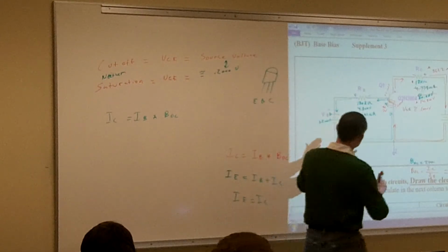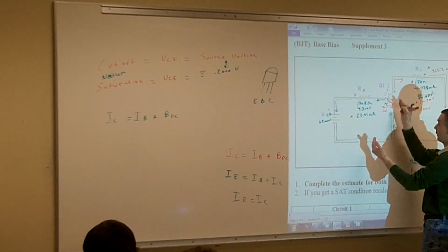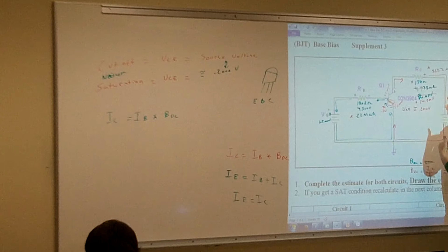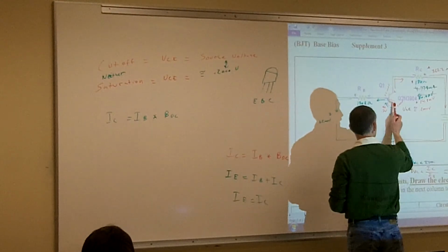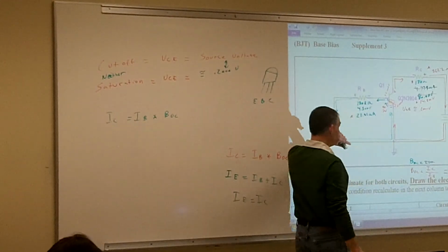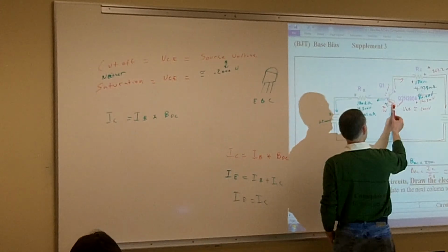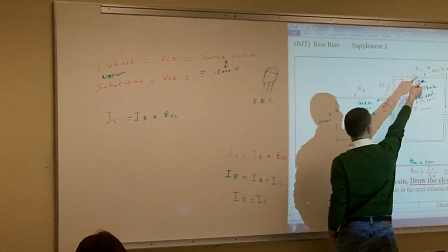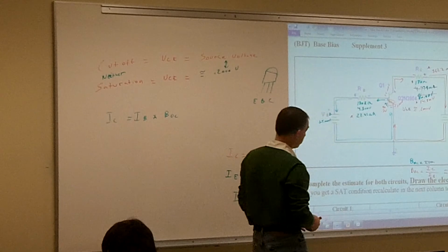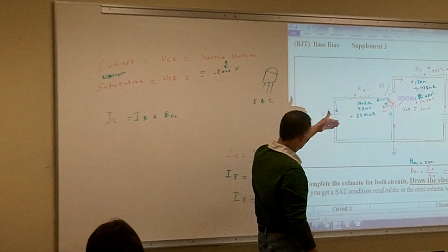Yep, two separate circuits. So nothing has to be recalculated in here because that's a whole separate circuit from here. The only thing that these two share is just that current of the emitter. Those two currents are going to combine right there, but 23.88 microamps is going to go off to the base, and the remainder is going to go back up through my collector.